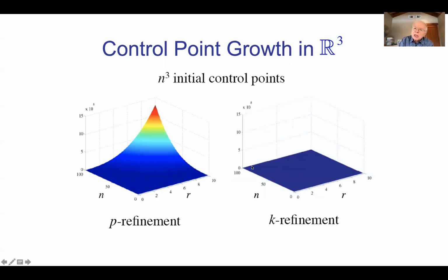You do the same with K refinement on the same mesh, 1,000,000 elements in these meshes, and you do 10 orders of refinement. And now what do you have? You have 1.3 million degrees of freedom, 1,000 times fewer. So you've got the same mesh, the same order of approximation, and you have many, many fewer elements.